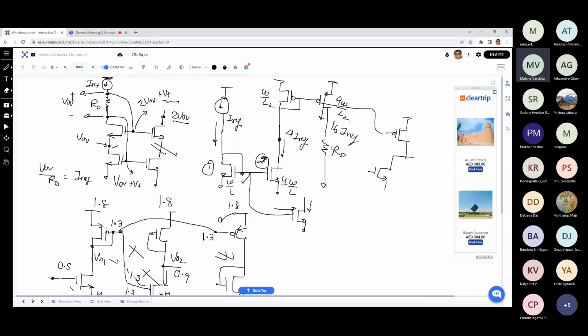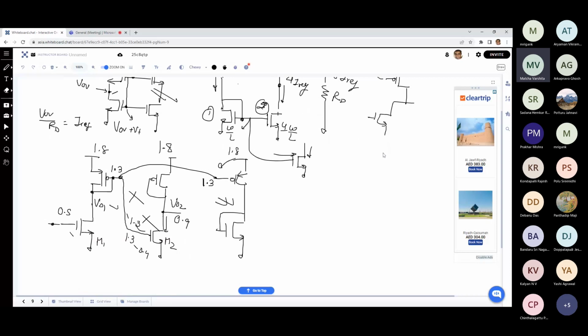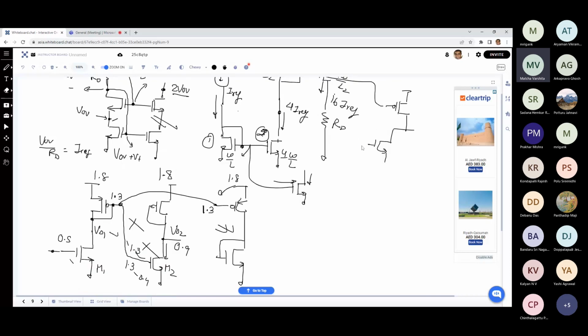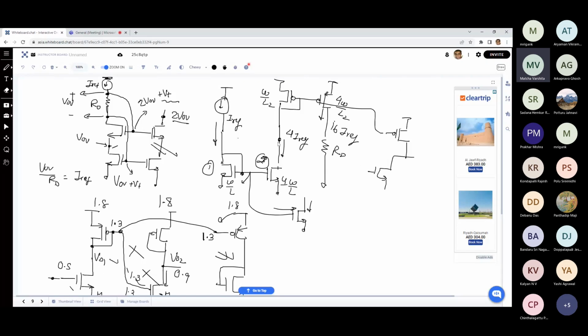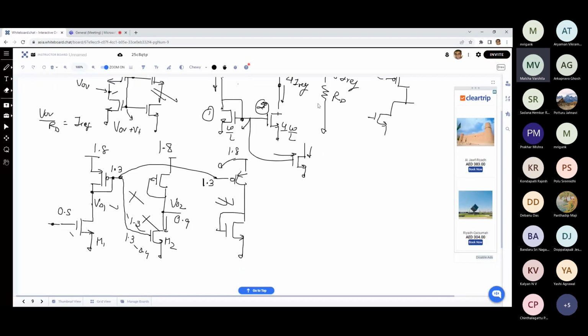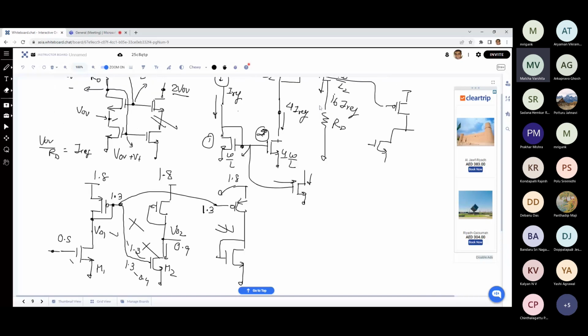So depending upon whether we are working with an NMOS input device or a PMOS input device, we may have to establish the right kind of bias currents using this kind of current steering. I'm just giving you the building blocks for the differential discussion. All these concepts that we are discussing here are forming the building blocks for your discussion on differential amplifiers and operational amplifiers, which are ultimately going to help you in working on real project problems. This is clear.